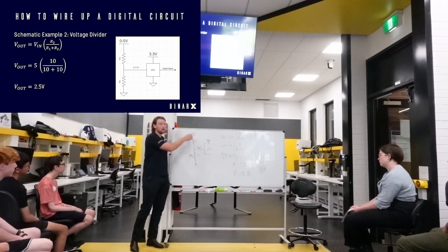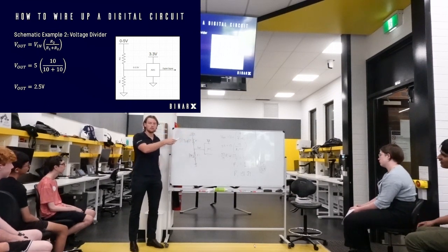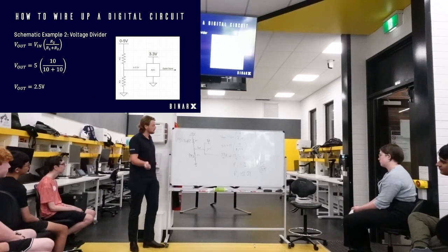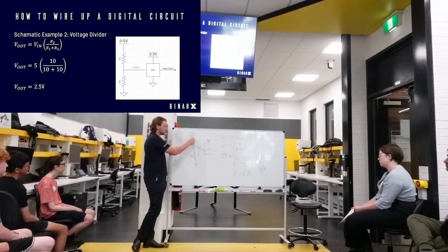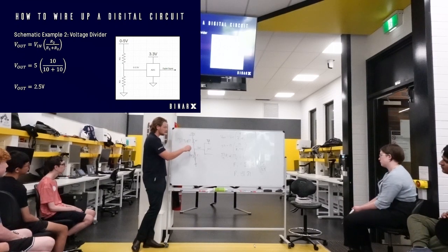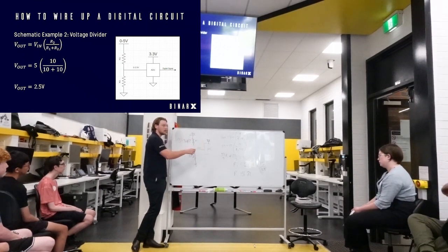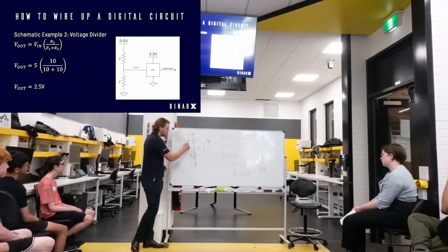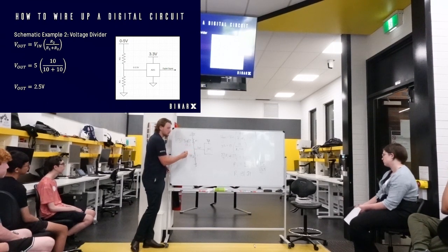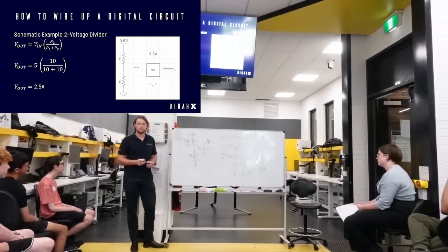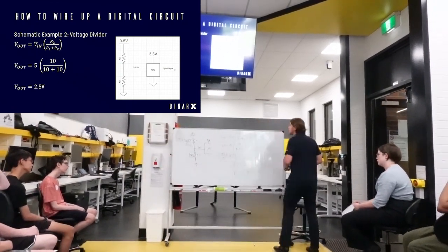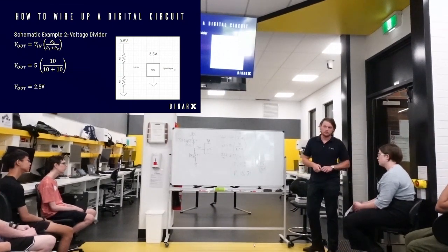We don't want our solar panels, let's say if this is our 15 volt solar panel, we don't want that to be sinking all of its power that we're trying to use to generate electrical power to run our battery, or to store in our batteries, or to run our electrical science. We're trying not to use that on just measuring it. So we use really high resistance values to make sure that we're not pulling a lot of current and it's really low power. So I think on the satellite we actually use mega ohm resistors. So they're even bigger, so the current is really low. Okay.